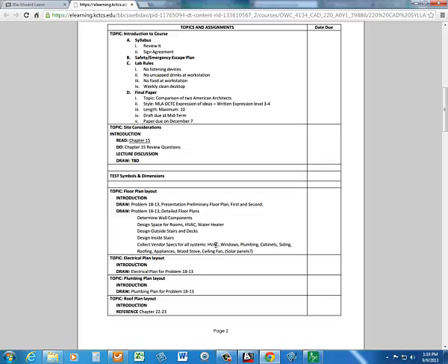Okay? So, and then you need the system specifications. If you're at least going to have heating, then what kind of heater are you using? You're going to use that wood burning stove that's in there, or you're going to have radiant floor heat, or you're going to use forced air, gas, or electric. But you have to have some kind of heating to keep it from freezing up. It's either that, or if you're not going to use it in the winter, then you have to have a way to drain the water out of the plumbing completely. So it's all the way out to the well. Or if it's in a semi-improved vacation lake area, it might have water supplied.